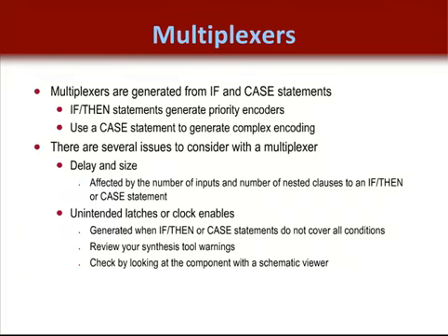You may have also heard that unintended latches or complex clock-enabled equations can be synthesized when your if-then or case statements do not cover all possible conditions. Fortunately, synthesis tools warn users when they are building latches, but they do not warn when the long clock-enabled equations are being built. That is why it is important that you verify for yourself what is being synthesized by your HDL. To do this, the best tools provide schematic viewers that show when this is happening.